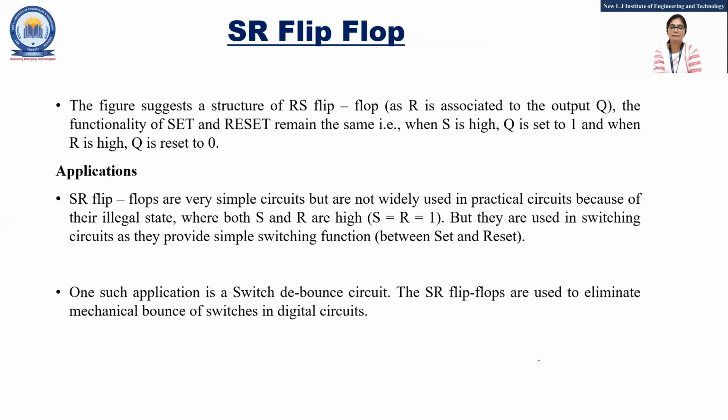Now we'll see the applications of the SR flip-flop. Generally, this SR flip-flop we are using as a switch debounce circuit. The SR flip-flops are used to eliminate the mechanical bounce of the switches in digital circuits.